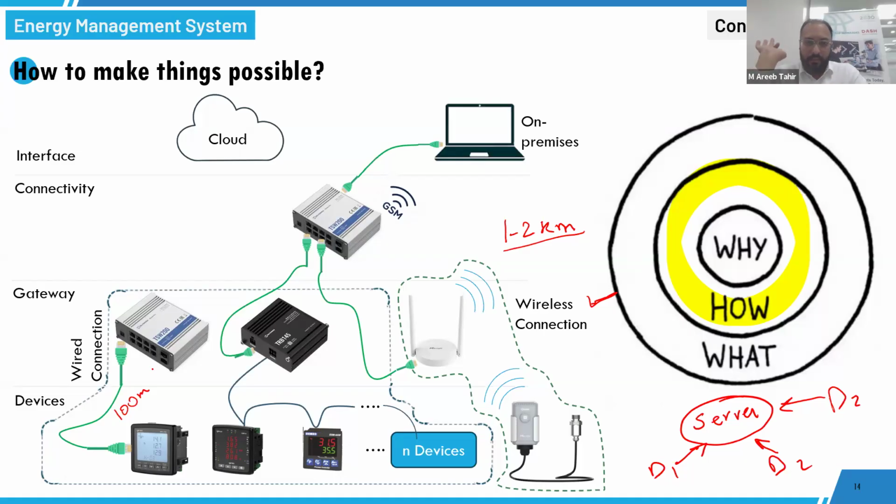But let's say you want a wired solution, or we think a wired solution is the best possibility for your application, then we can offer a daisy chain type of connectivity, which can be up to 700 meters. And it can be used for 31 devices. Normally, we take 31 devices in a loop, or we can have a repeater to extend.